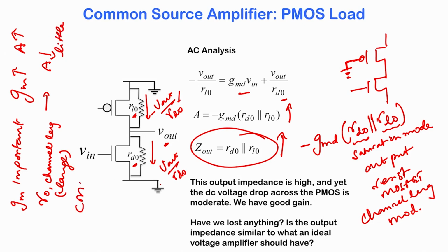And CMOS technology can give you very high gain, and the gain for most voltage amplifiers is a combination of the effective transconductance of the driver and the effective output impedance of the circuit. Okay. So, this is the take home message from everything that you have learned. So, CMOS, the combination of PMOS and NMOS transistors, is a very powerful tool.